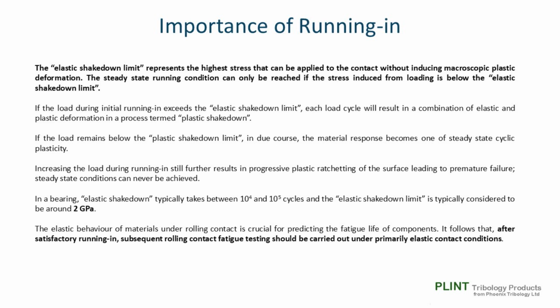Increasing the load during running in still further results in progressive plastic ratcheting of the surface, leading to premature failure. Steady-state conditions can never be achieved. In a bearing, elastic shakedown typically takes between 10 to the 4 and 10 to the 5 cycles, and the elastic shakedown limit is typically considered to be around 2 gigapascals.